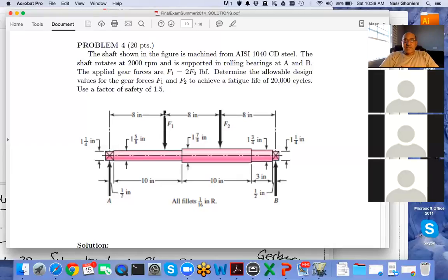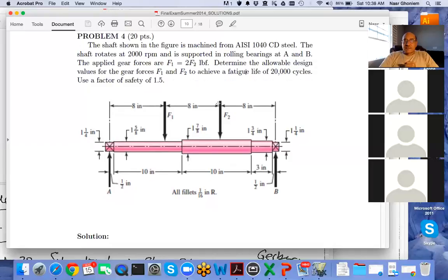If we have F1 and F2, you will have some kind of inclination, bearing down not vertically on the shaft, but at an angle. Well, in this case, we will have to decompose the forces F1 and F2 into their components. You have a vertical component, which would be F1 times the sine of 20 degrees, and then a horizontal component, which is the complement to that. So it's just vector decomposition, right? This is the next problem.